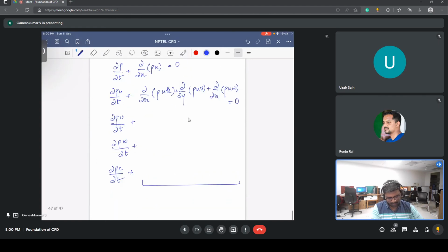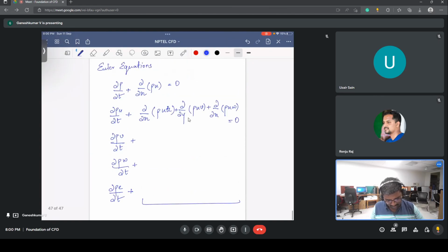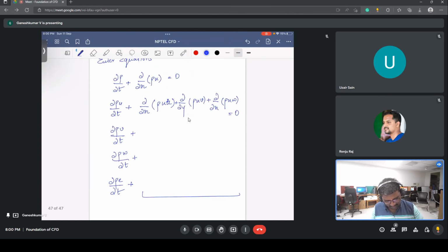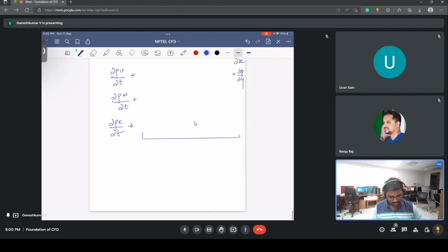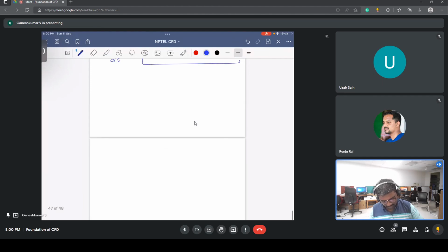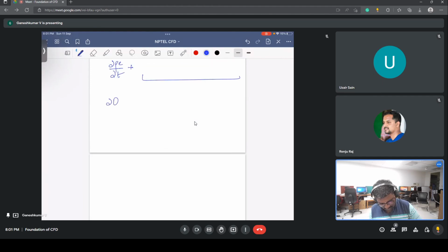So basically what I was trying to say is, as we have a pressure gradient here also, it is not equal to 0, dou p by dou x, similarly dou p by dou y, but the viscous terms won't come, or we are neglecting them because it's the Euler equation. So what they will do, in a coupled approach, is make something called a vector form of the equation.